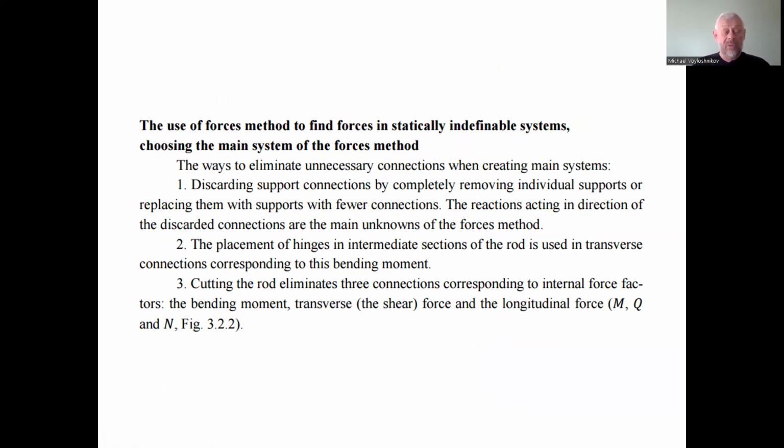The use of the forces method to find forces in statically indeterminate systems, choosing the main systems of the forces. What are the ways to eliminate unnecessary connections when creating main systems? First is discarding support connections by completely removing individual supports or replacing them with supports with fewer connections. The reactions acting in the direction of the discarded connections are the main unknowns of the forces method.